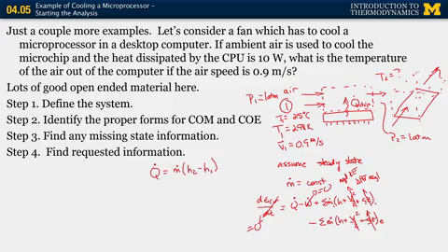Okay, but that's not the temperature. We're looking for temperature. I used the conservation of mass. I used the conservation of energy. Those are my two big guns, my best tools. What's left? I need another equation to connect enthalpy to temperature. And at this point, you should all be having the aha moment that it's air.